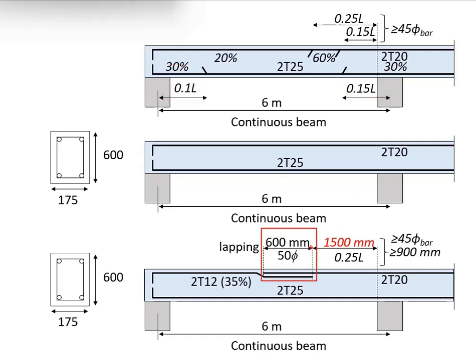By using the principle of doing the bar lapping starting here, that means if you want to reduce the bar size, your lapping will have to start here. And this is likely will be the lapping region here. When this is relatively short and you need to provide lapping, it is very likely to end up with more or less the same amount of reinforcement bar here.